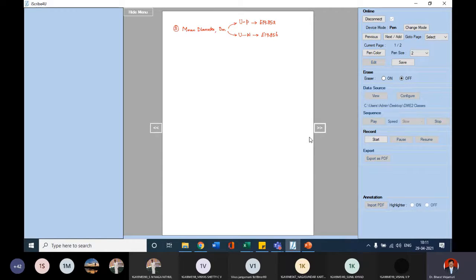Let's keep the data handbook with you so that it is more comfortable to follow. It depends on which theory you are solving for. The next equation is about axial force, which we call FA. This is also based on uniform pressure theory and uniform wear theory, so once again we have two equations: equation number 19.86b and equation number 19.83.